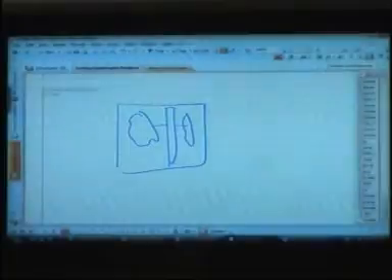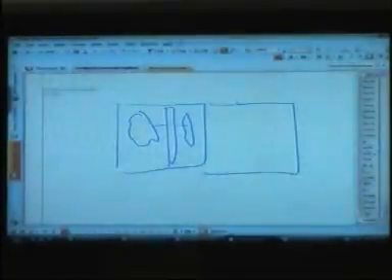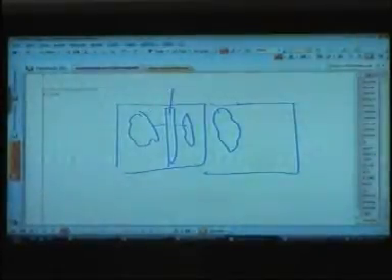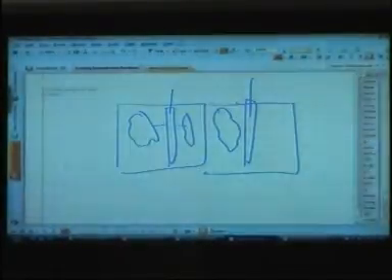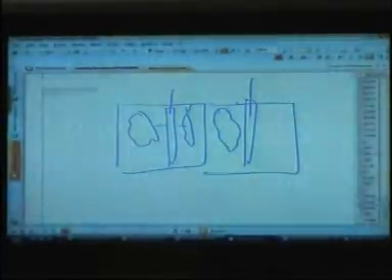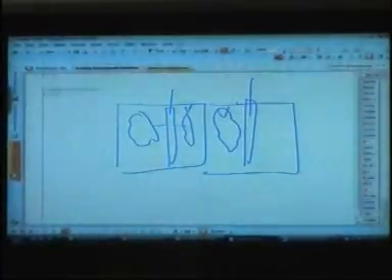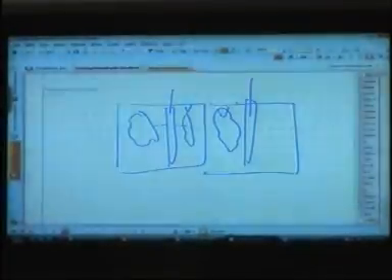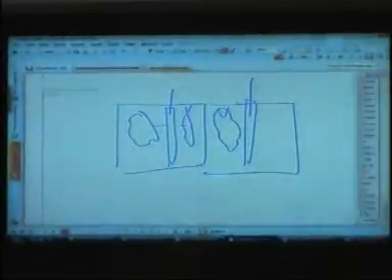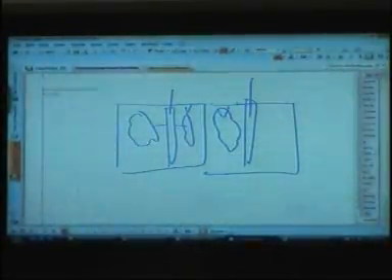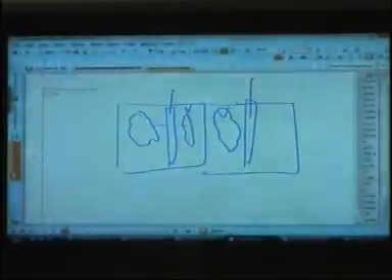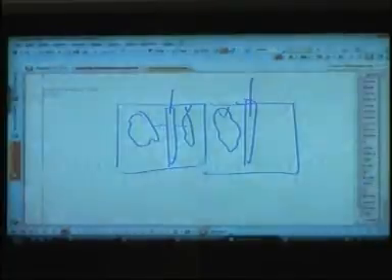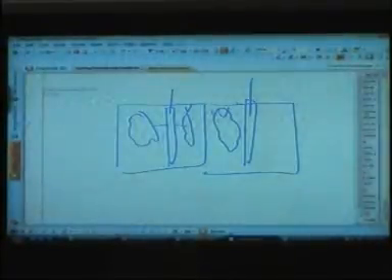Okay, and now you put another person's module here, and he also has a combinational cloud. Now the register to register timing is from this register to that register. So this logic was working at 10 megahertz, this logic was working at 10 megahertz, but once you put them together, it becomes a bigger combinational cloud, and it may only work at 5 megahertz, and now you have problems. And they are very difficult to fix, because somebody has not really catered for this, because an individual engineer is only focusing on his part, that yes, my design works at 10 megahertz.